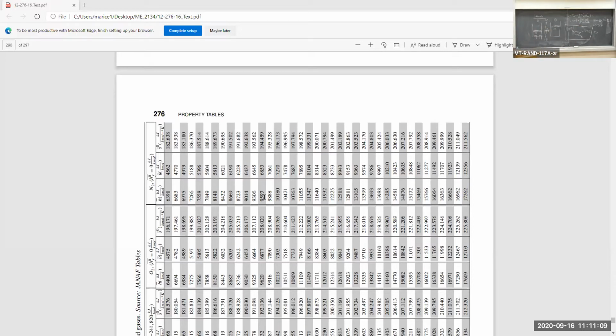The temperature we got before, 56.7 plus 273, was about 329, about the same thing. So we got very close to the same temperature for variable specific heat. So the actual temperature of the system, neglecting round-off error or any errors in the calculation, is 329.6 degrees Kelvin, using an interpolated temperature from table B12.